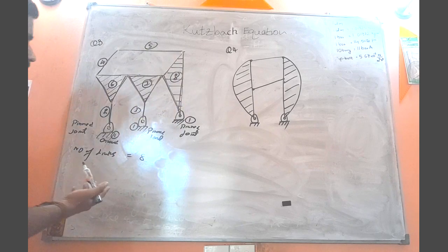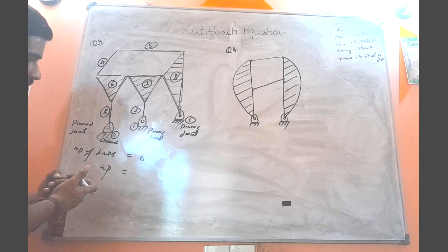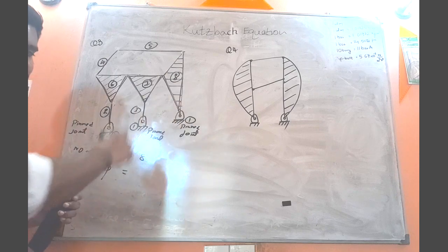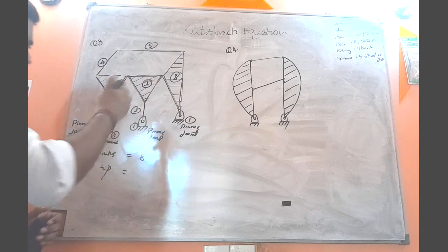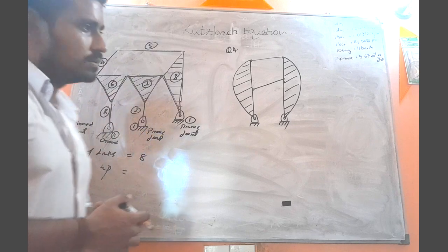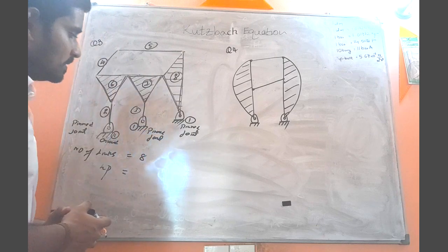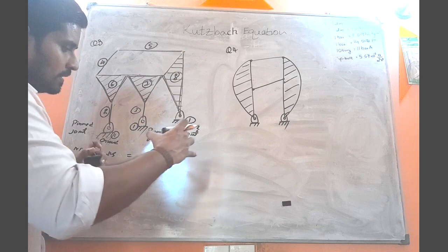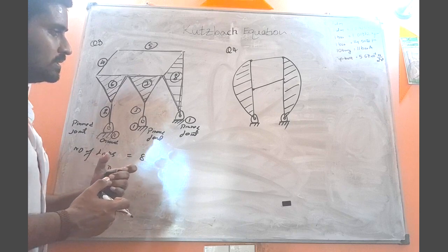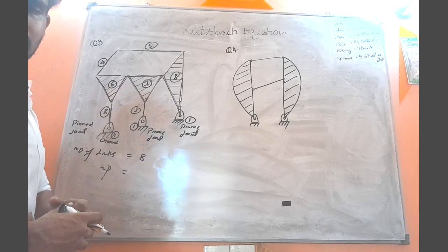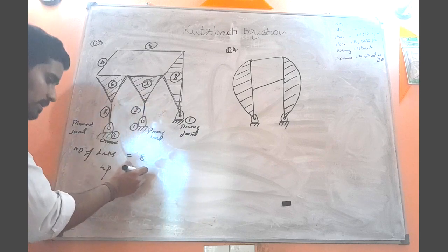As you can see, there are no higher pairs, or in other words, point connections. We cannot see any line of action, such as I have discussed as an example. In this problem we cannot observe anything like geared mechanisms, or rollers, or in other words tire and rod like connections. We cannot observe such types of connections, so there are no higher pairs. So higher pair is 0.